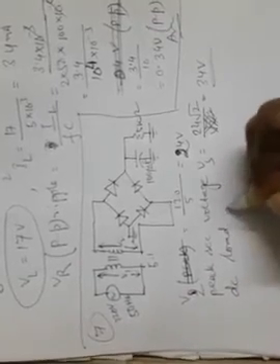So now assuming an ideal diode and small ripple like the previous two problems, the DC load voltage will be VL, that is 34 volt, since the ripple is small. So this whole voltage is considered as the DC voltage, not mixed up with AC or small ripple, and the diodes are ideal. So no barrier potential of the individual diodes will be subtracted from here.